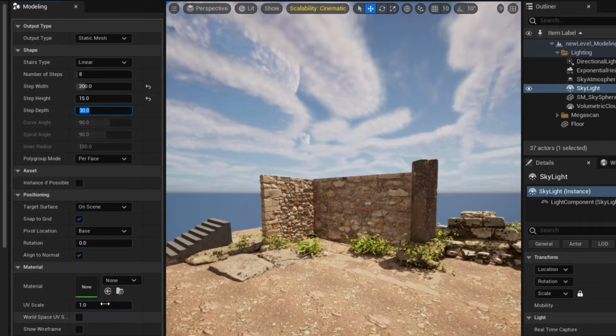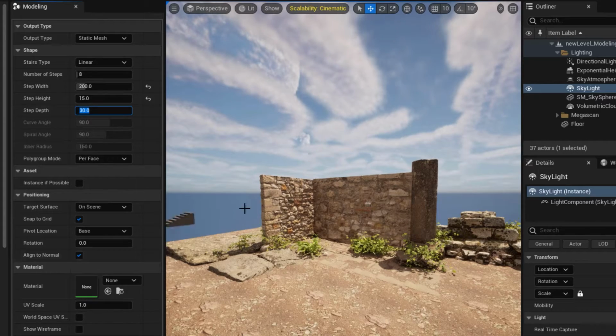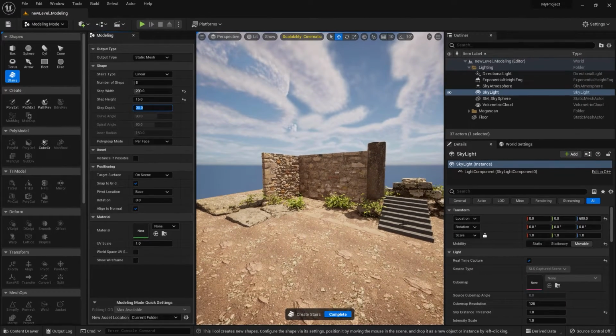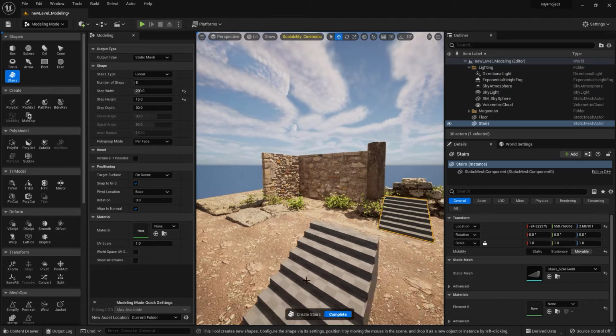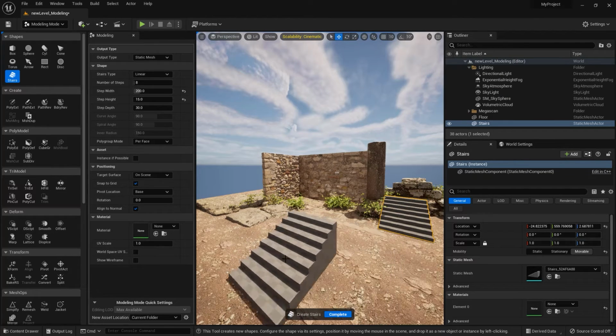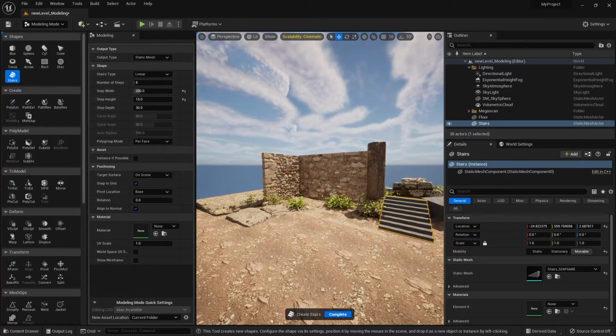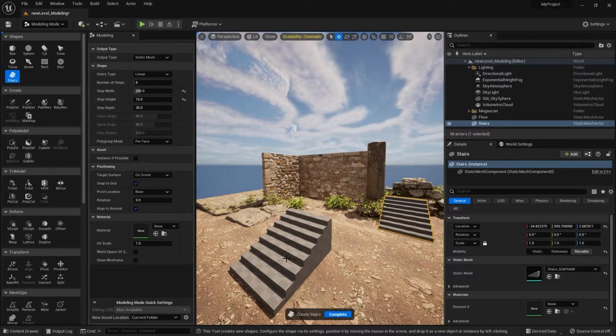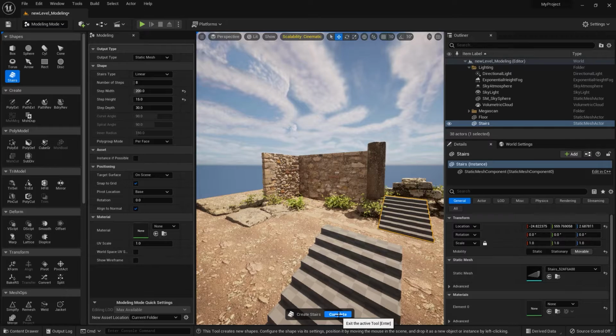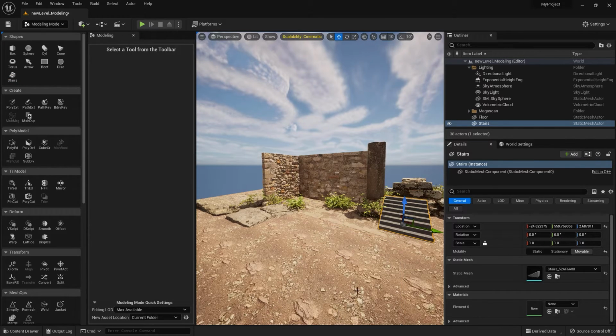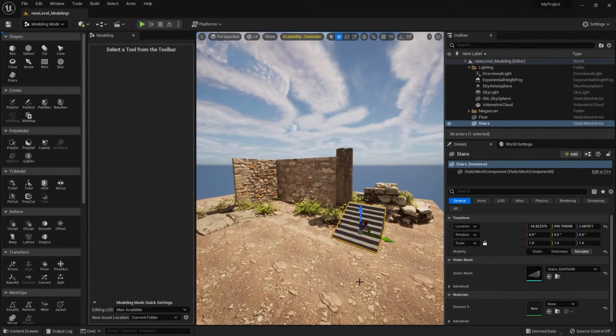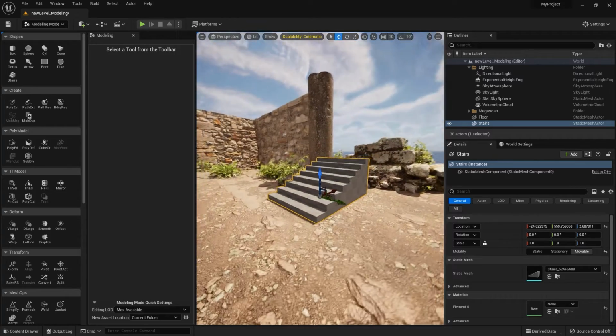You can have a material ready to go, so assign the material here and create it. So I click, and then I still can click and create more staircases, so I can actually go in here and create another one right next to it, which I don't want. And once you're done, you go ahead and click on complete. And that's what you have, a brand new staircase.